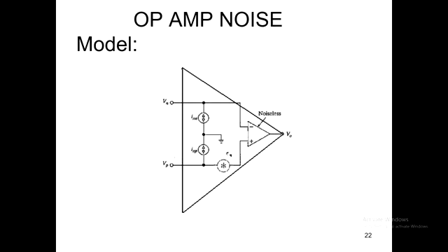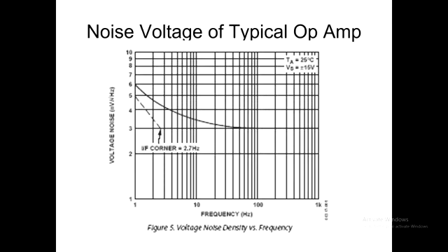So the very act of hooking a resistor here that's meant to provide some gain will introduce a pathway for a noise current to produce a voltage that then gets amplified along with everything else, including the signal that we seem to have forgotten about for the time being, but that's what we're here for, amplifying a signal, yet inadvertently going to amplify that noise as well, regrettably.